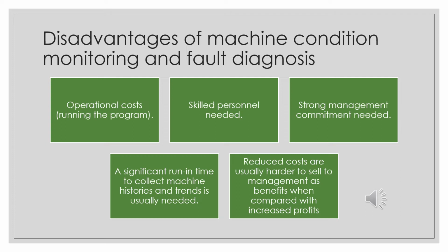Next are the disadvantages of machine condition monitoring and fault diagnosis. The first one is that operational cost for running the program will increase. Skilled personnel needed. Strong management commitment needed. A significant run-in time to collect machine history and trend is usually needed. And reduced costs are usually harder to sell to management as a benefit when compared with increased profit.